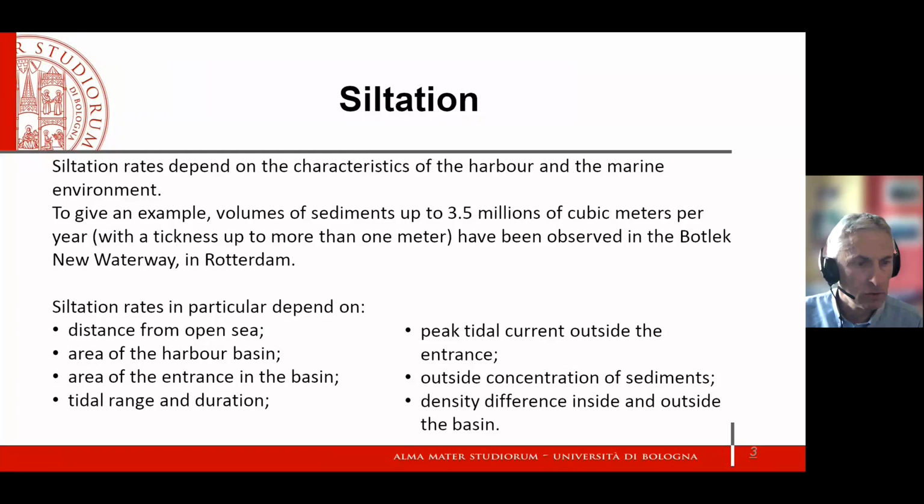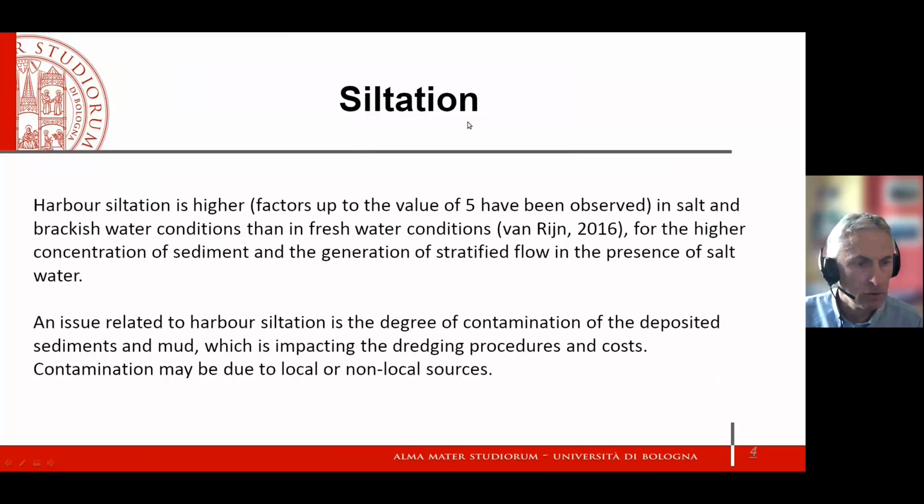Also, the peak tidal currents are, of course, relevant. The outside concentration of sediments, of course, and the density difference of sediments inside and outside the basin, because the greater the gradient in concentration and the greater the flux of sediments into the basin. All of these features have to be considered in our modeling, in our assessment of dredging.